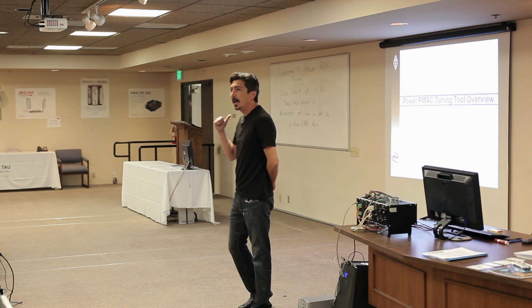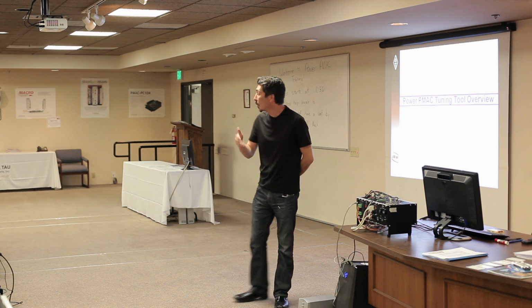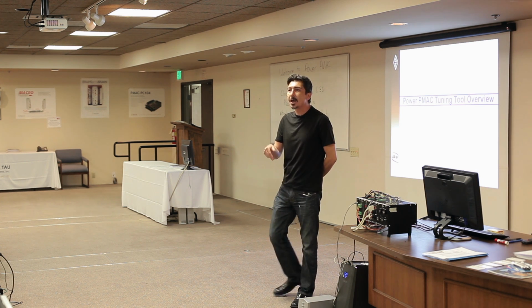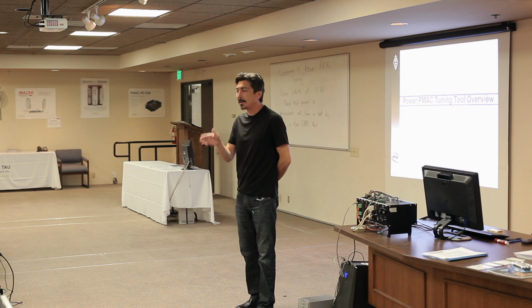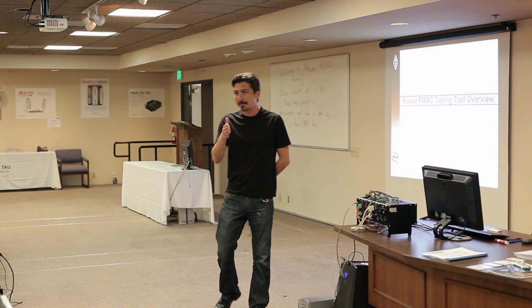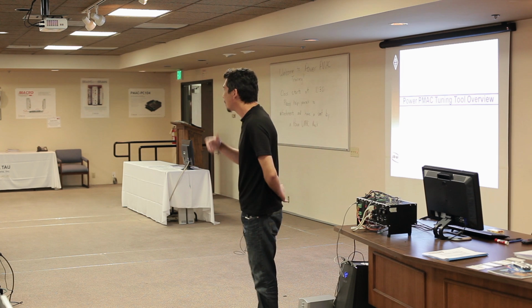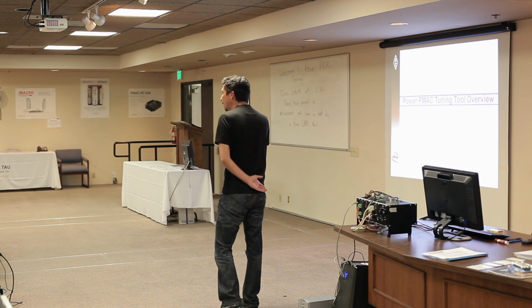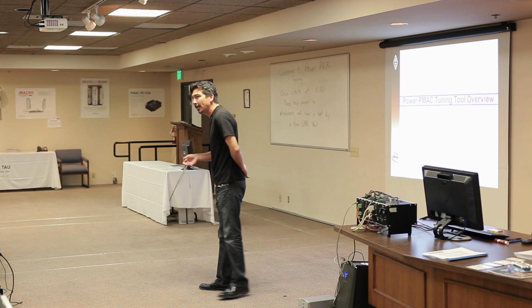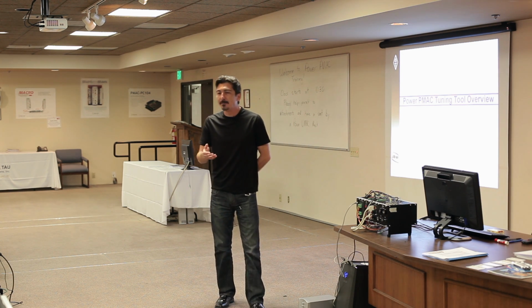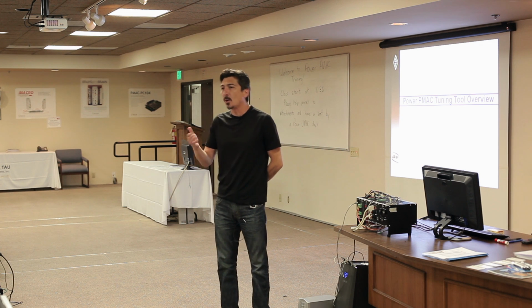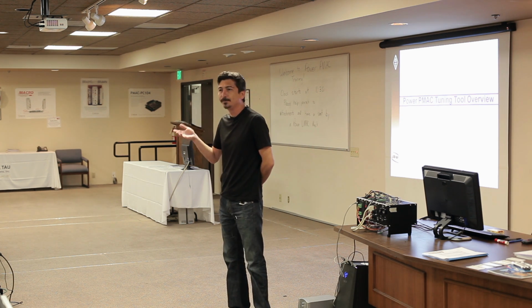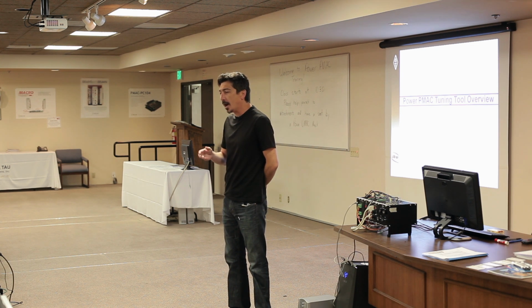And before starting, I can tell you, for those of you who know about our older generation controller, Turbo PMAC, there's a big difference in terms of speed, of course, much more powerful CPU. It uses floating point mathematics, which allows us to have a much more general control algorithm. Our standard control algorithm, I'll show you, on top of some other algorithms built in the firmware, is capable of basically having 3 notches. It has a 7th order filter.